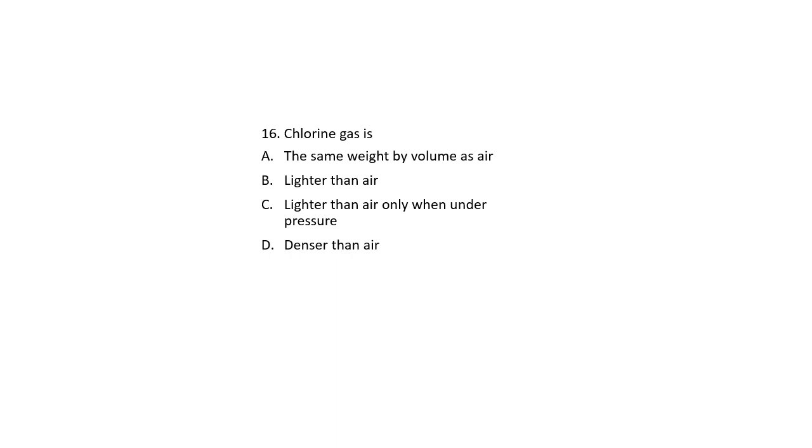1 part per million is the short-term limit, about 15 minutes. 10 parts per million is immediately dangerous to life and health, IDLH. 30 parts per million, immediate chest pain and vomiting. 1,000 parts per million, death can occur in just a few breaths.